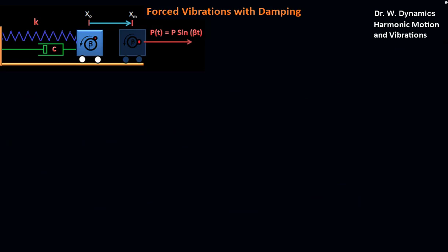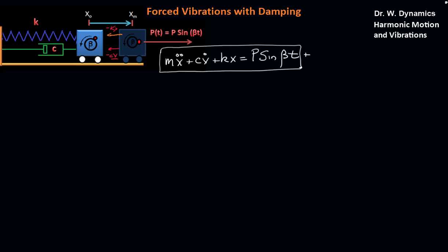Here we look at the case where we have forced vibrations with a damper installed as well. And our free body diagram would still look the same. We'd have minus kx, and we'd have minus cv. And our equation of motion would reduce to, and what we can see here, if we think of the plus 0 being over here, that we still have our x homogeneous solution for damping, and then we'll also have our x particular portion over there, and that will end up being x total. And if we put all the pieces together, we'll end up with this following relationship.